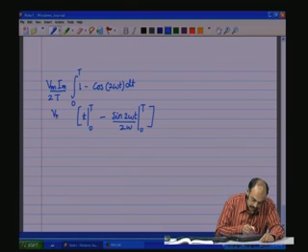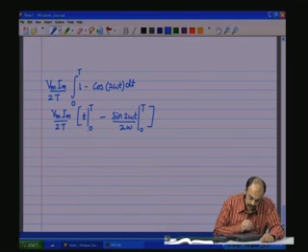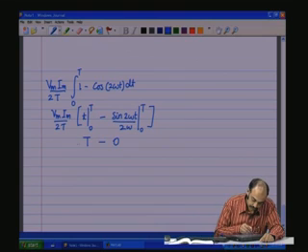This of course is multiplied by Vm Im by 2t. So, here this is t minus 0, that is t, and sine of 2 omega t, with omega t equal to 2 pi, will result in sine 4 pi or sine 0, both are 0, and therefore, this will be 0 at both the limits, and this means that we have Vm Im by 2. This is the average power, P average.